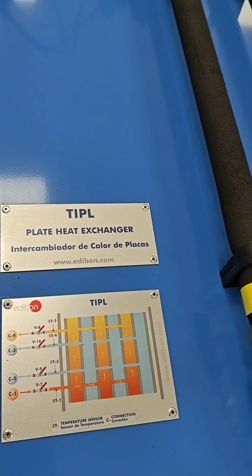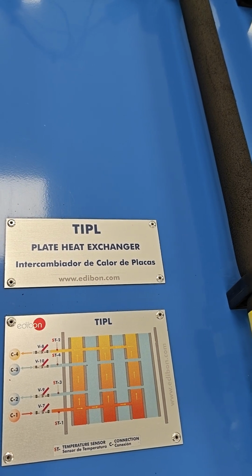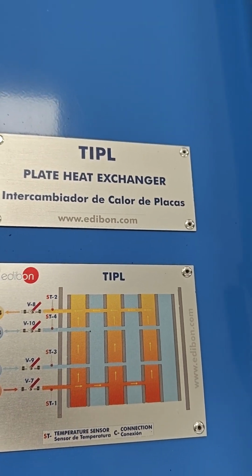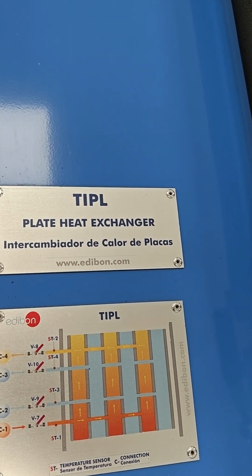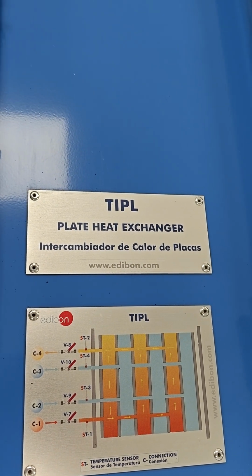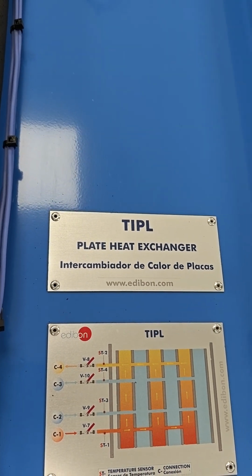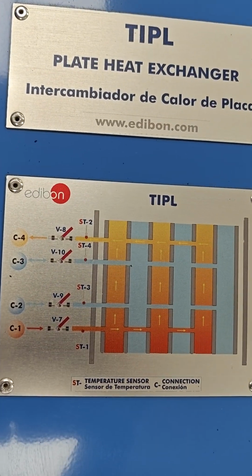So they do not mix with each other, they are separated by the plates. It is a real boundary, and as they travel through the exchanger, they are exchanging heat. Basically, from the hot fluid, the heat is given to the cold fluid. So as the hot fluid enters and travels, it is losing heat and it comes out cooler, and the cold fluid, as it enters and travels, it picks up heat from the hot fluid and it comes out hotter. So one fluid will cool down, the other fluid will get heated up. That is how the balance of energy is taking place, and the heat exchange, heat transfer is taking place.